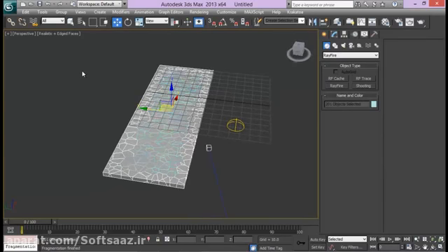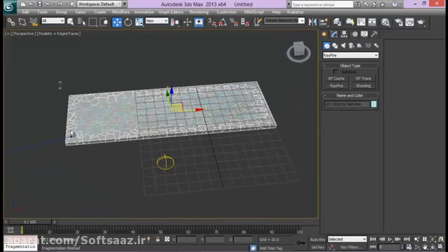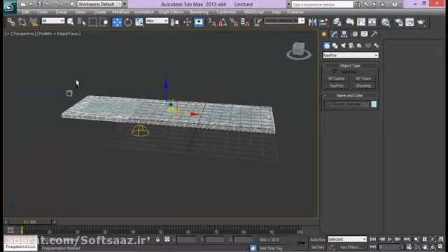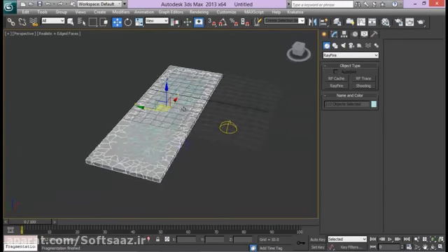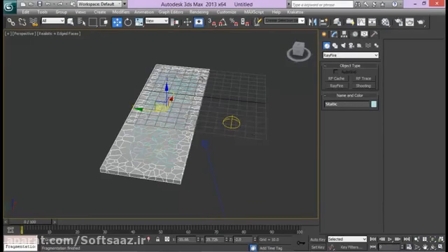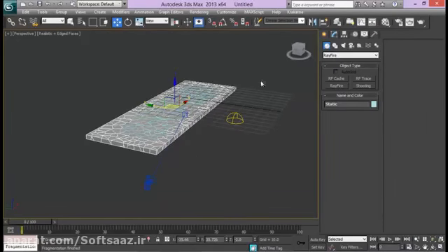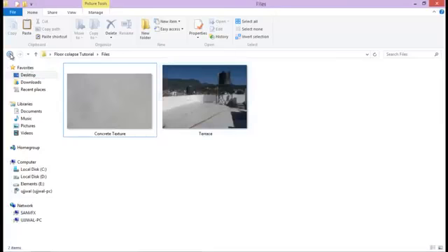Now, I guess I need to select a little more from here as well. Okay, and I have selected this camera tip. Let me deselect that. Let me go ahead and group them, and I'm gonna name it static so that they are not gonna be part of my simulation. Also, why I did that is because if you make all these pieces fall down, then we'll have this sharp edge like collapsing. Let us see in our scene right here.